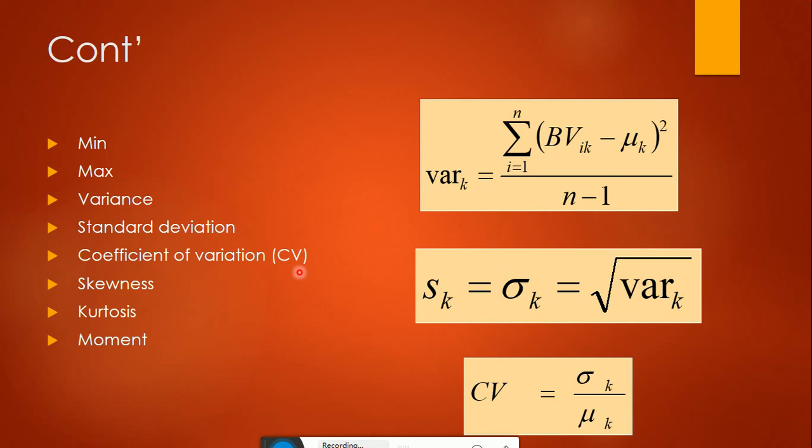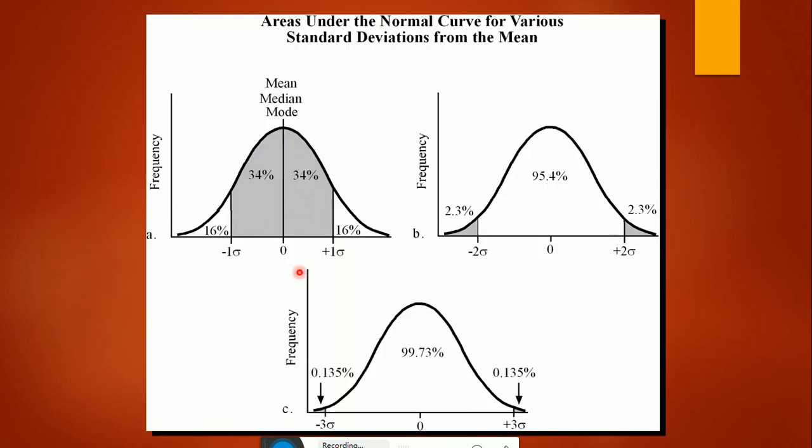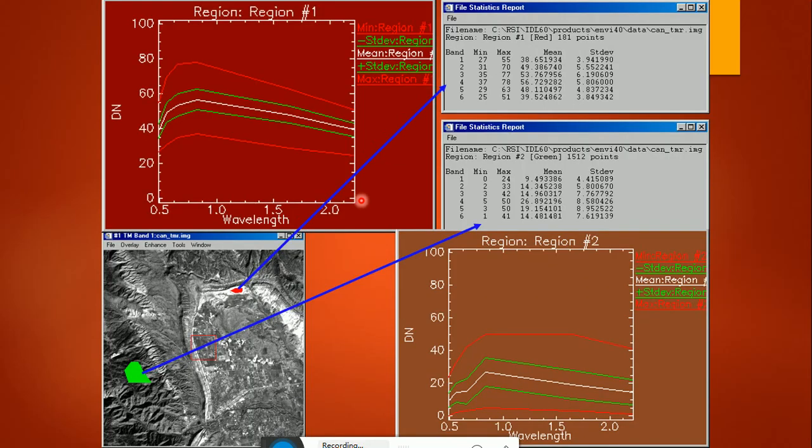Come to the geometric correction. Geometric correction includes correcting for geometric distortions due to sensor or geometric variation, and conversion of data to real world coordinates, for example latitude and longitude. The systematic or predictable distortion can be corrected by accurate modeling of the sensor and platform motion and the geometric relationship of the platform with the earth.